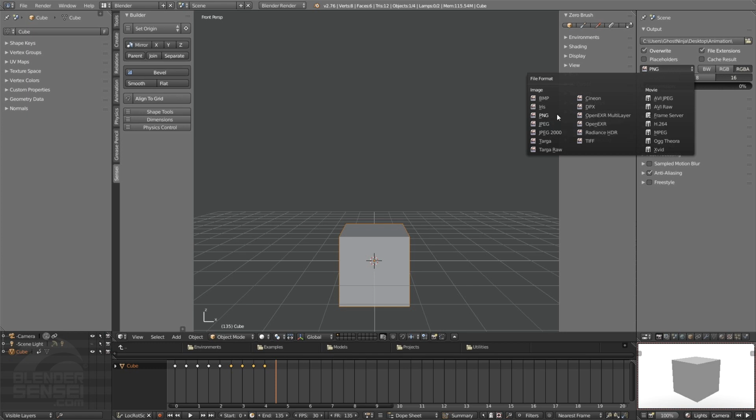And this gives you a huge amount of control in the final compositing process of your final animation when you're bringing together sound clips and multiple video clips and stuff like that, especially if you're using software like After Effects or Adobe Premiere or Final Cut or something where you can do lots of cool stuff to the layers. So any file type that you choose to render your animation out as under this image category is going to create a folder of rendered still frames starting from the first frame to the last frame in the animation. When you're working with animation, this is the way to go because it will produce the highest quality video in your final result, and also it gives you the maximum amount of editing control when you're bringing clips together and making your final product.